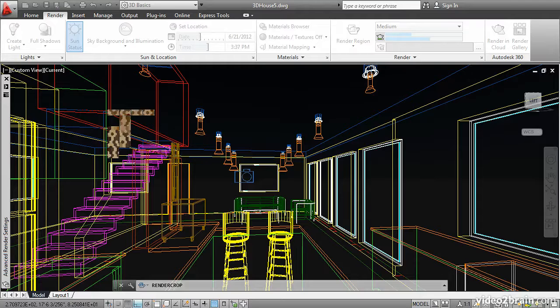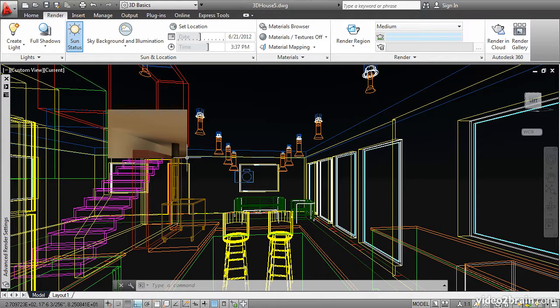The Final Gather results are starting to come in, and at first they're very blocky. The way it works is it progressively refines the results. The squares get smaller and smaller until eventually we'll have a nice continuous gradation of light. That's starting to look good. Okay, I think we're ready to make a final render. Go up to the teapot icon, open its flyout, and choose Render.